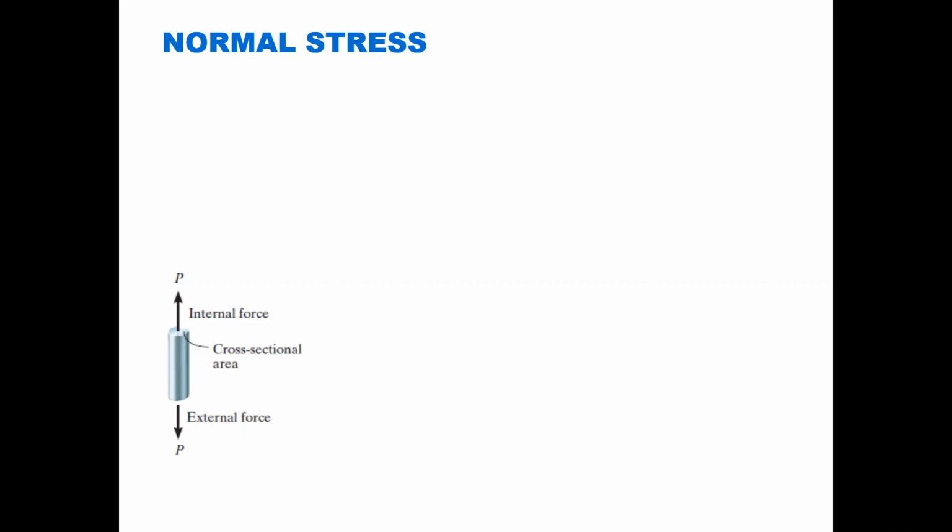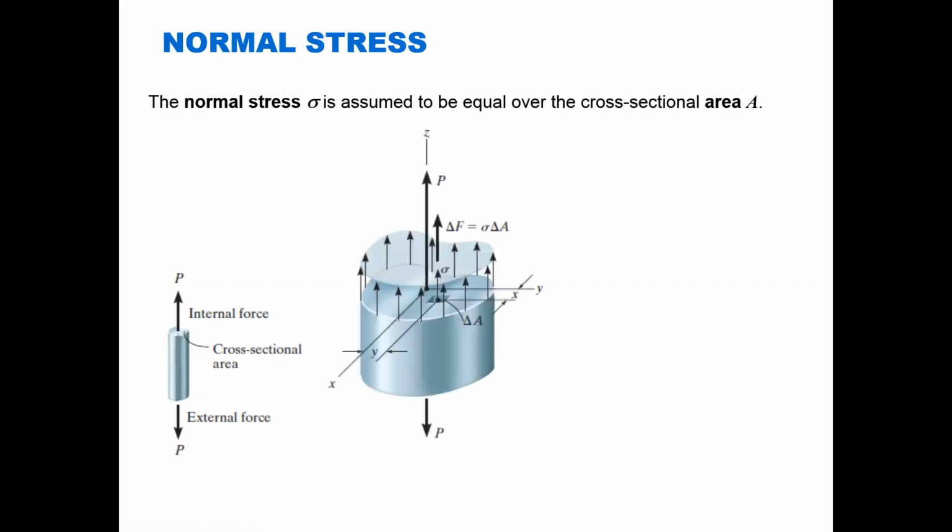Now, the thing to remember about this class and throughout the whole course is that stresses develop based on the internal forces. We're going to have several types of external forces on our structures throughout the course, and there will be various internal forces that we'll learn about as well. This is just one of those internal forces, and this internal force is normal to the cross section, so it's going to develop what are called normal stresses.